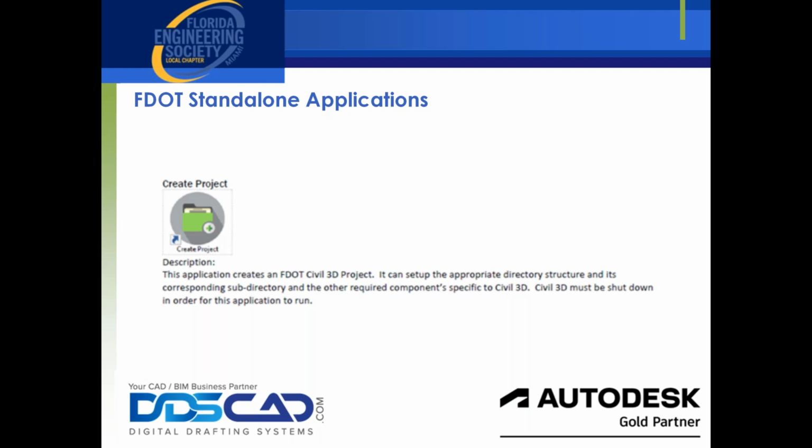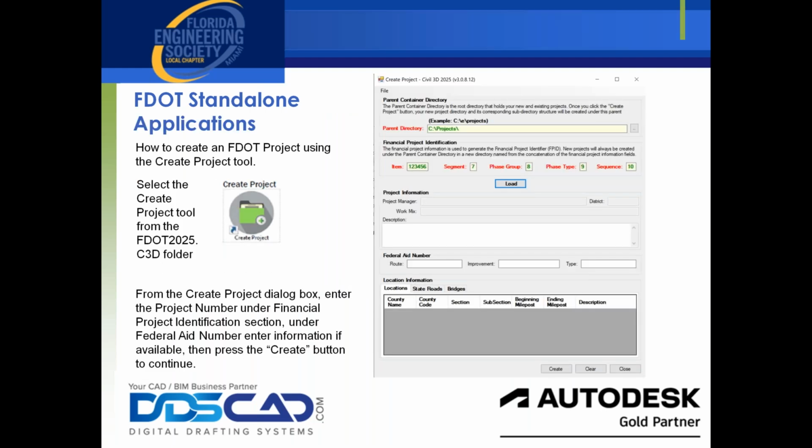So the Create Project tool is an application that lets you create an FDOT Civil 3D project, which is something that you have to make the state kit work correctly, right? So it sets up the appropriate directory structure and its corresponding subdirectory and other required components specific to Civil 3D. Again, Civil 3D must be shut down in order for this application to run. All right, so when you click on that, you get the Create Project dialog box that pops up.